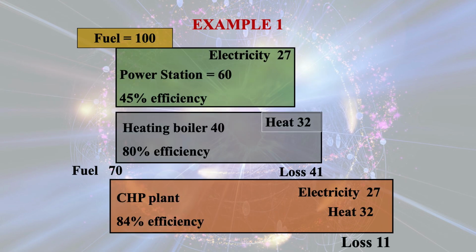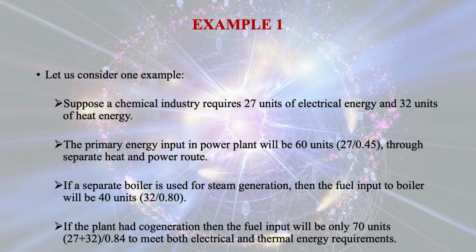Heaters 1 and 2 thus operate at pressure P2 and P3 respectively. The amounts of steam m1 and m2 extracted from the turbine are such that at the exit from each of the heaters, the state is saturated liquid at the respective pressures.